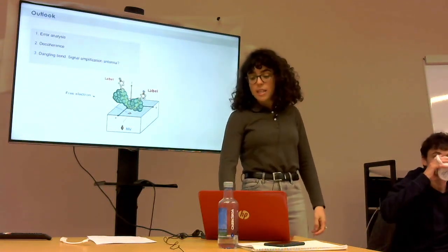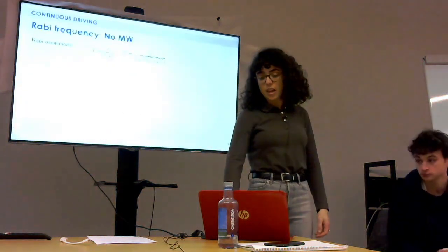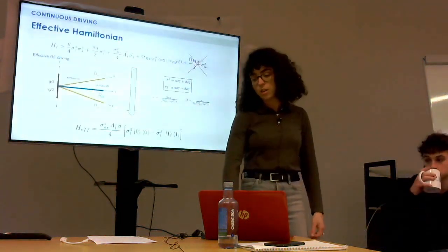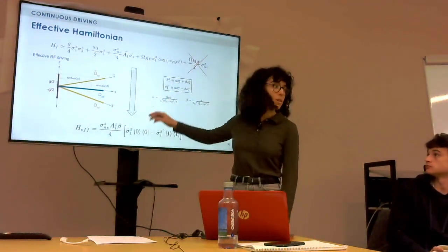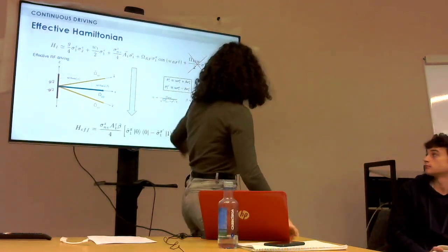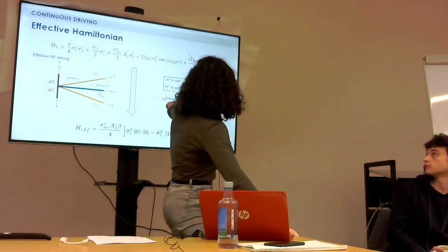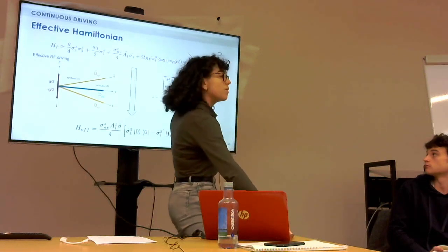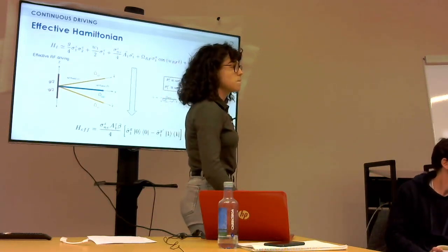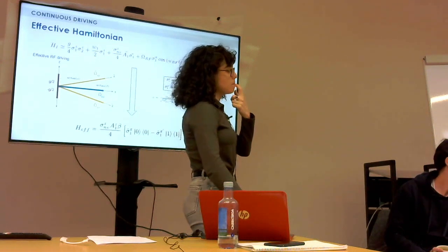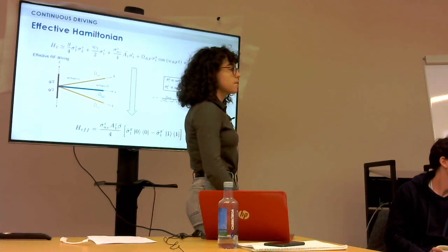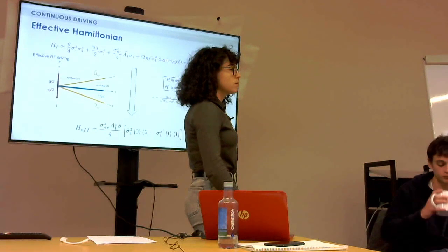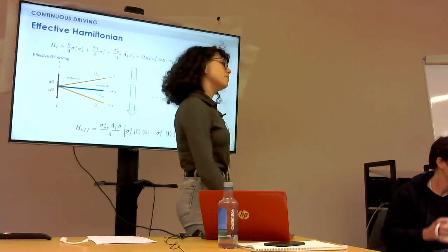So we think that the errors will be smaller when we are extracting G from beta than when we are extracting G from alpha. Because in the case of alpha, we have G down here, and with beta, we have it up here. That makes sense when one analyzes this situation, but with errors and small precision, you always extract from this square root, which is complicated, in particular when omega Rf is much higher than G. However, in beta, it is linearly there.